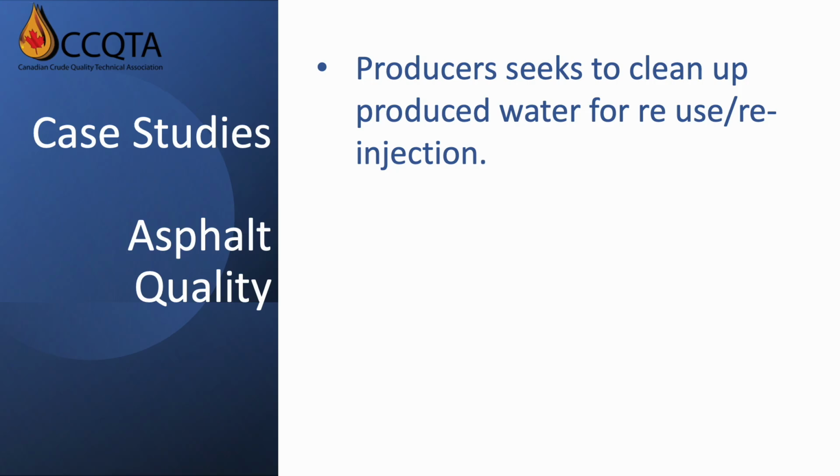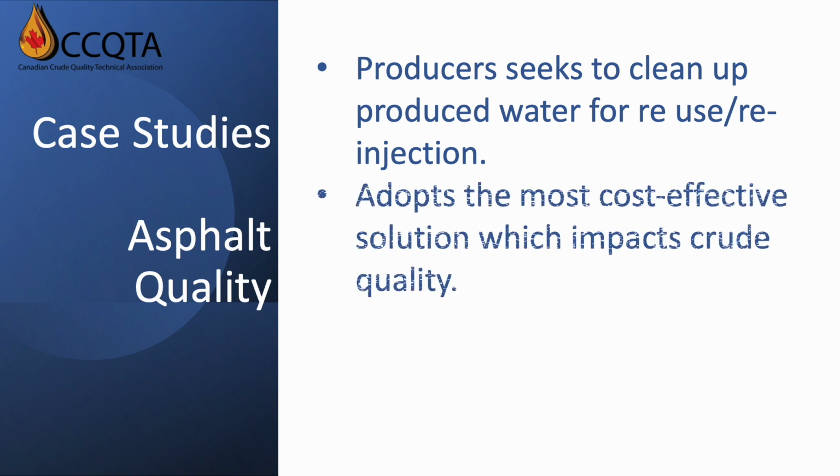One involved installing mechanical filtration equipment, which necessitated significant investments in the equipment, including a process for disposal of the recovered oily solids. The second option involved the injection of a high molecular weight cationic polymer in a dissolved air flotation unit on the water stream, which would then redirect solids and oil waste back into the produced crude. The chemical option was selected since it was deemed more cost-effective and eliminated the need for solids disposal.